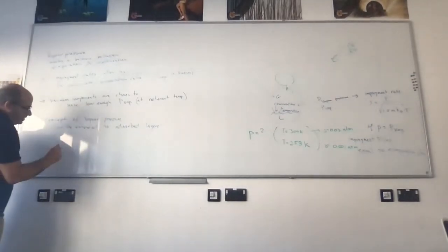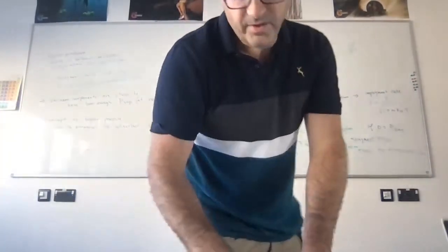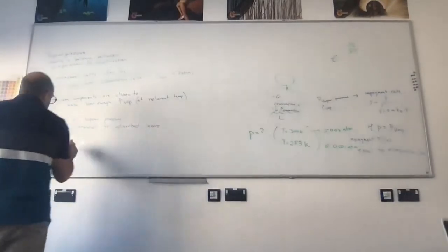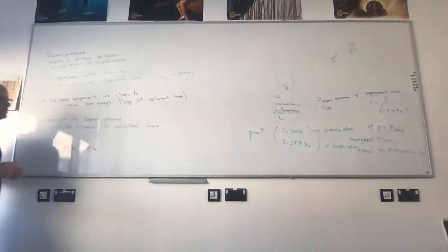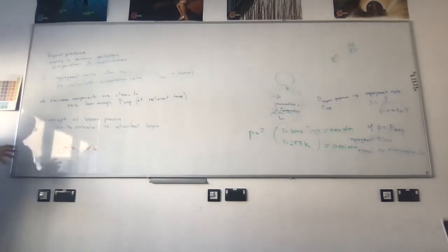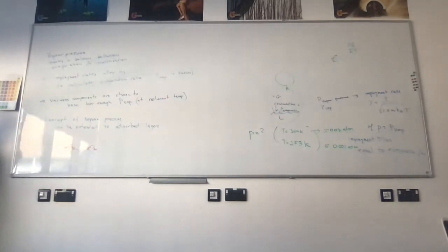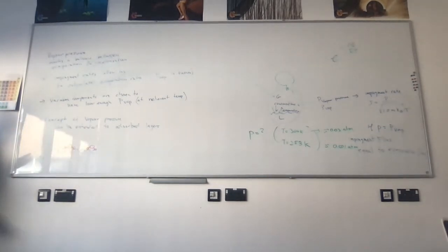What I mean by that is that if we have a surface of a material or whatever, and we put some contamination molecule on top of it. Let's say this is my contamination molecule. It looks like water, maybe. The amount of adsorbed water onto that surface also introduces a concept of some kind of a vapor pressure. So to have, let's say, half of my surface covered with water molecules, there'd be a certain rate of impingement, which would be equal to the rate of evaporation, okay?